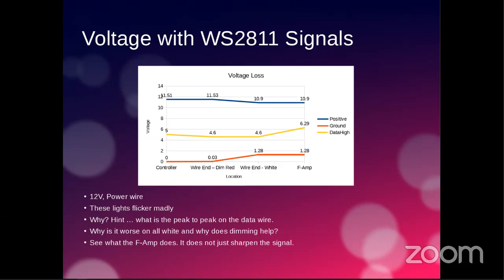Once you go through the first pixel, in many ways it will act like an amp. It will boost the voltage coming out of the pixel back up to 5 volts. Now that does change. That's very true with regulated pixels. With resistive pixels, that's not quite as true. With a regulated pixel, the voltage going to the 2811 chip is pretty much always 5 volts until the input voltage gets quite low.